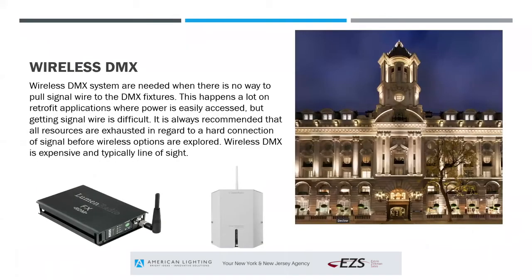There are also wireless DMX options. Generally speaking, the controller itself is not transmitting wireless DMX, but it's sending a DMX hard signal to a wireless transmitter, and then that transmitter will send out to a receiver. We see this a lot on retrofit applications where we can't always access new data signal wire.